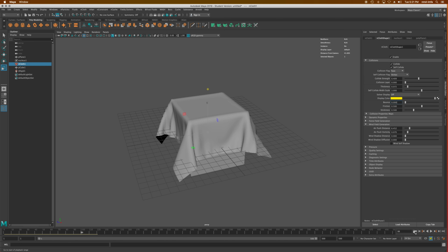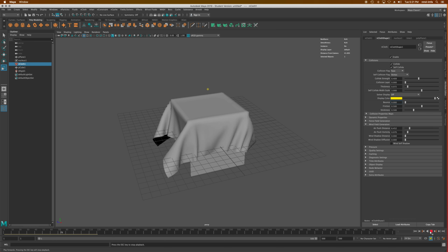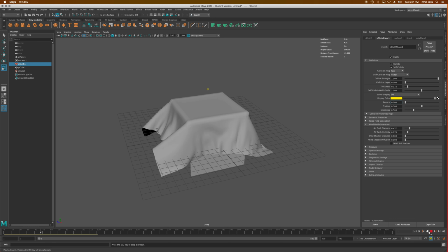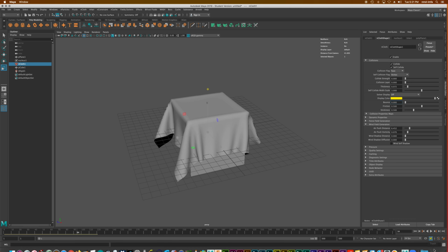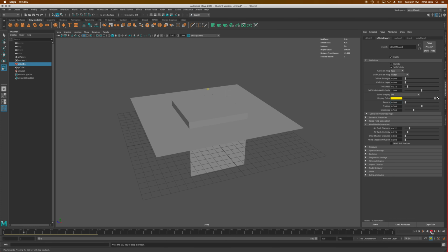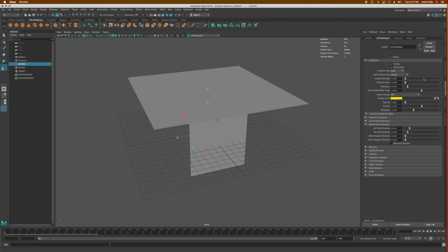Let's bring that in again. Yeah, the collide strength makes it a little stiffer when that's up. If I go all the way to 1, there we go, versus no collide strength, it passes right through, right? So you want it to collide, and you can play around with that to see how much the collision happens. You can also play around with this thickness setting here.